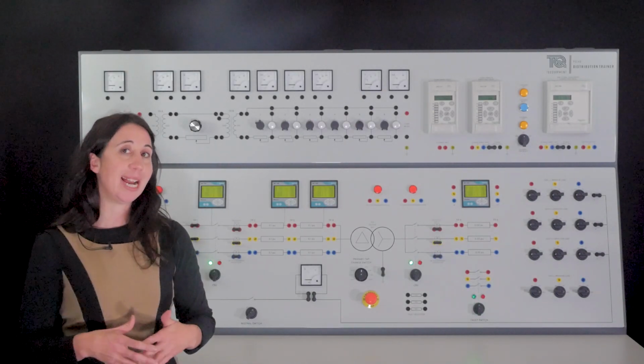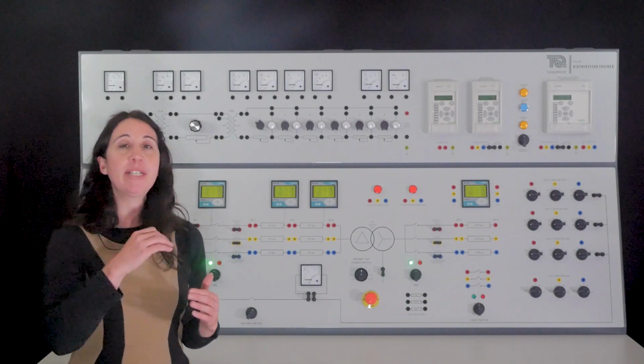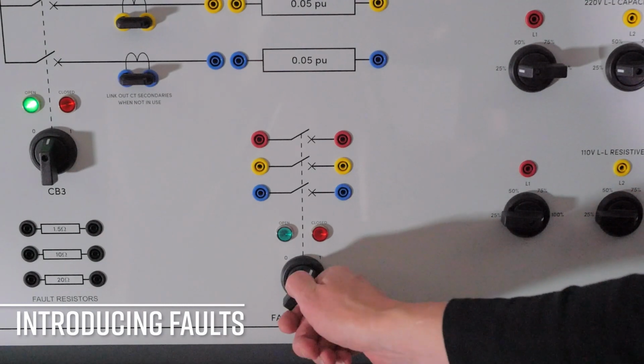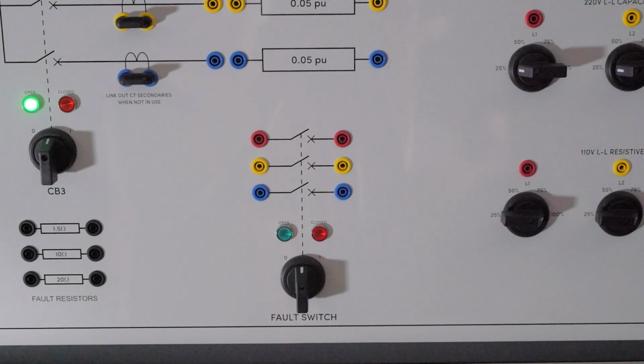The protection relays are connected into the distribution system using current transformers, which are provided on the secondary side of both transformers. These protection relays are stimulated by applying various kinds of faults onto the system. The fault application switch provides an easy way to apply line to line to line, line to line to earth, and line to earth faults on the system.